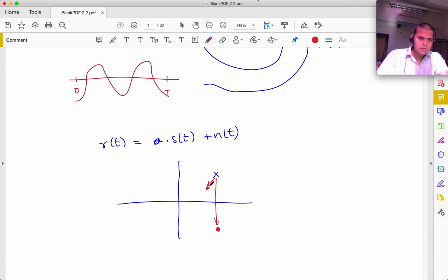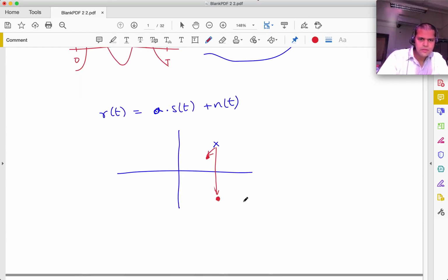Okay, so essentially we don't know exactly what's going to happen because the noise could be large or small, it's unpredictable. But we know the probability distribution of the noise, and we know how likely it is that this particular constellation point gets shifted too far off. Let's say it goes into a different quadrant. We know the probability of that happening because the white noise has a particular distribution.